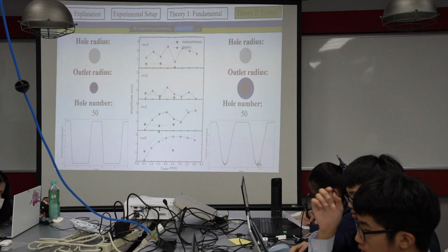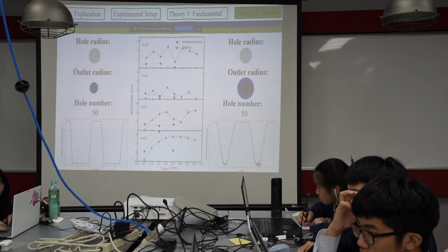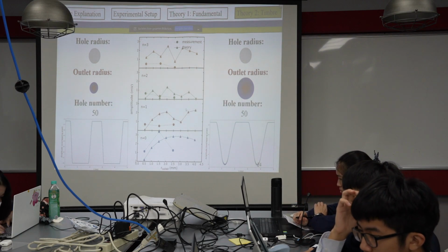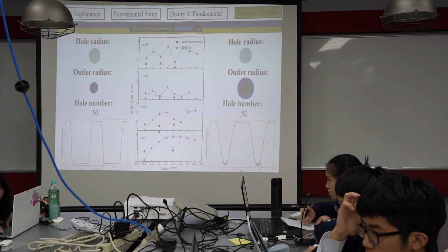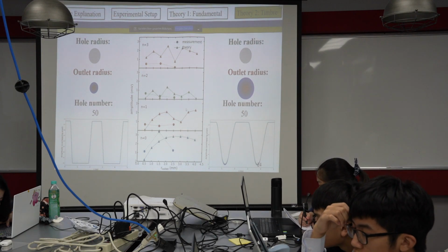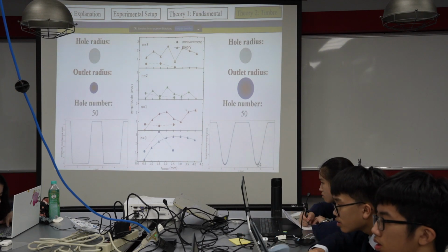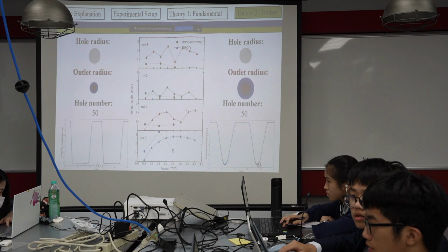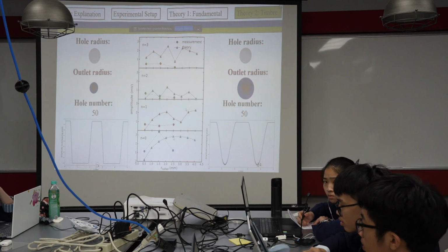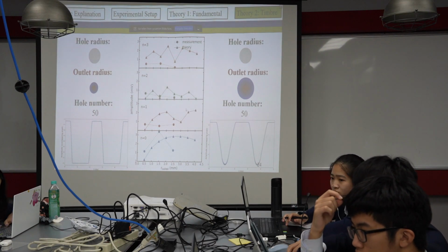Changing the varying parameter to the outlet radius, we get these graphs. In this case, it is important to mention that I adjusted the pressure to get the same absolute amplitude with every outlet. We can see that the absolute amplitude does not fit quite as well as for the hole radius, but the progression is still valid within a certain error margin. The deviation at the 2.5 millimeter outlet hole is quite large sometimes and can be explained as this outlet was in fact not circular but rectangular.